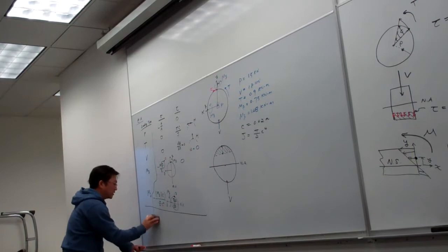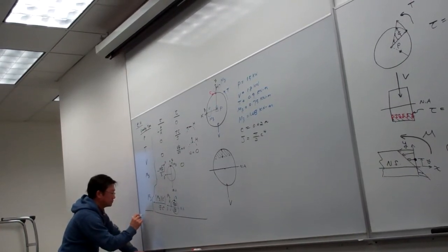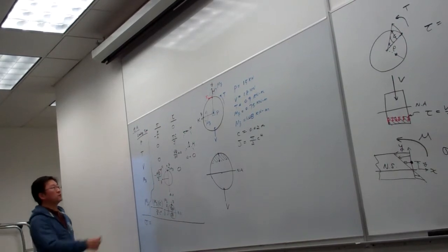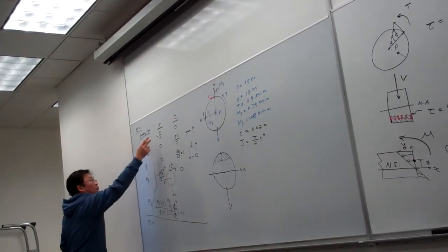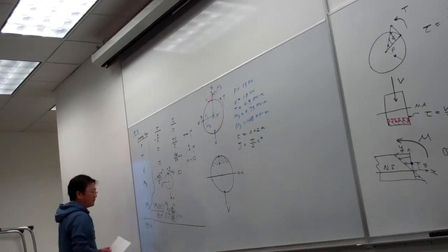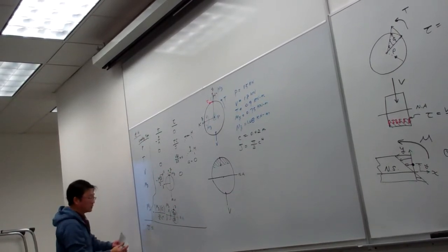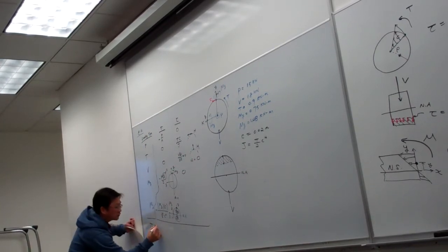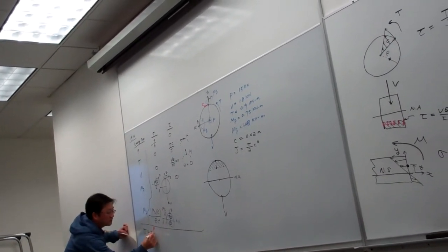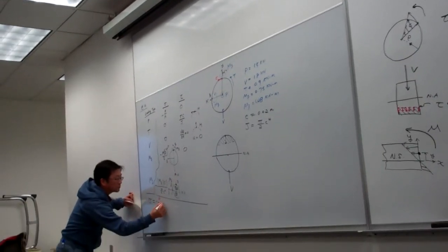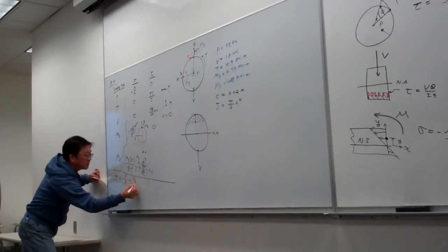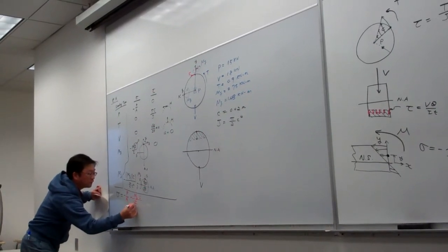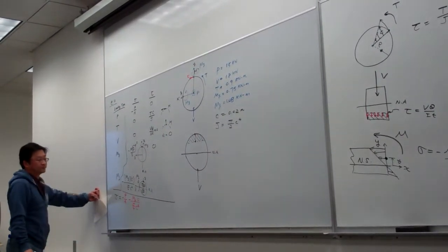So therefore we take the summations. Sigma will be total equal to the five terms added together. So that will be equal to the compressive term due to this one, and then this is compressive, Mz times c, pi over 4 c to the fourth power.